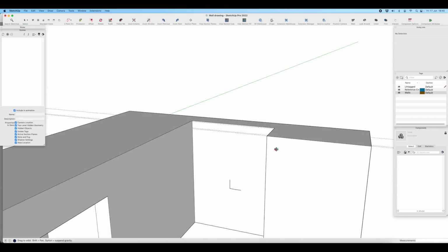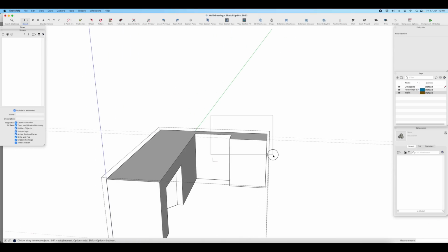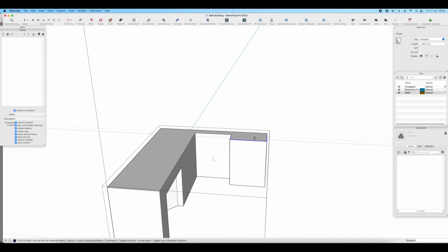So in order to dip that down, what I could do is double click into that wall section, grab this bit of the wall, and then try moving it vertically downhill. But you see it makes a bit of a mess of all the top of the walls there, because it's trying to move these three lines vertically downhill, and it's got a bevel across from these points here which are all fixed.